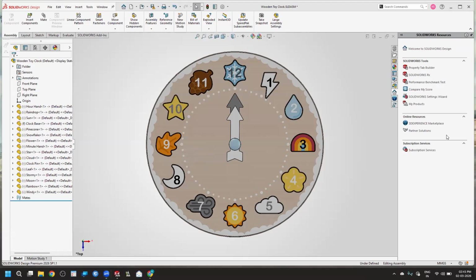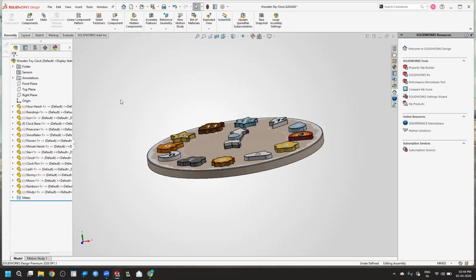Good morning, everyone. In today's video, I'm going to explain the exploded view, which is in the SOLIDWORKS assembly section. And note it down that this exploded view can only be used in the SOLIDWORKS assembly section. We can't use it in the part modeling, the drawing, or any other sections except assembly. And the main use of this exploded view is to explain the interior parts which are hidden inside a component.